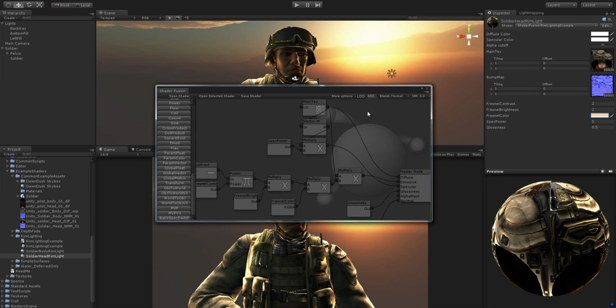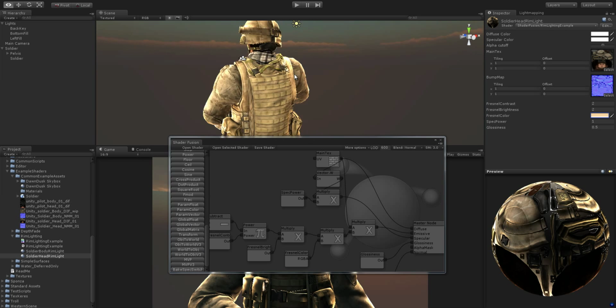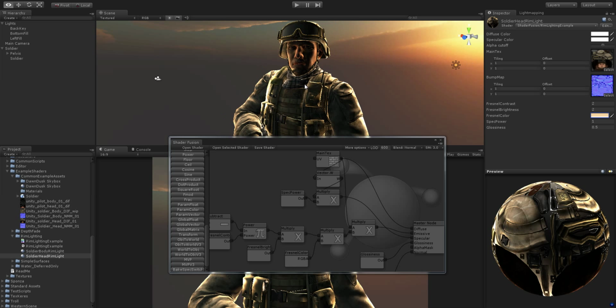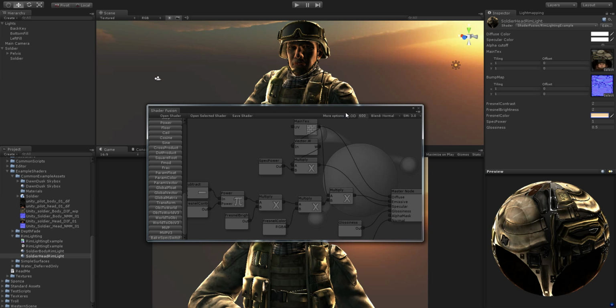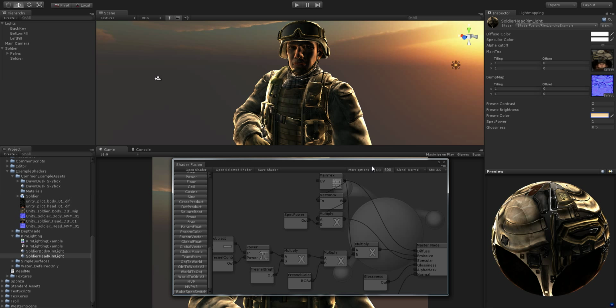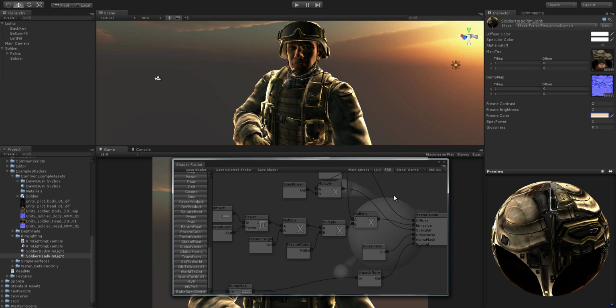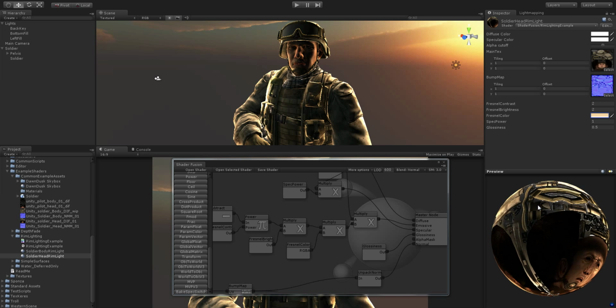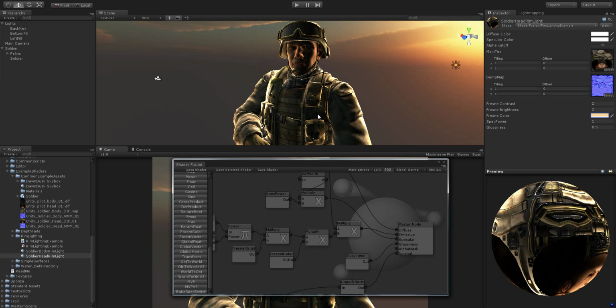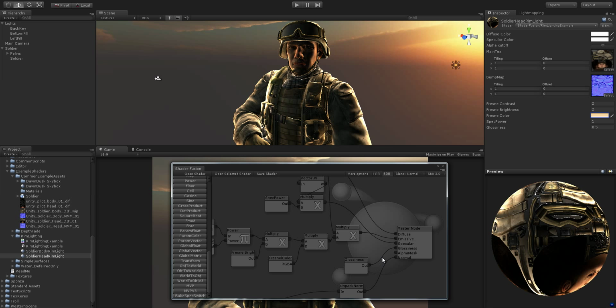So that's basically how to create a simple fresnel shader to simulate rim lighting. There's some more advanced stuff that you can do, like adjusting the amount of specular using the rim lighting, and even adjusting the glossiness, which can cause some nice effects when making a planet shader.